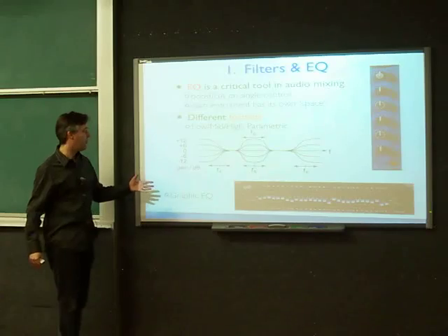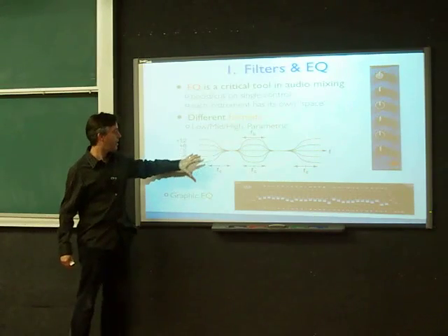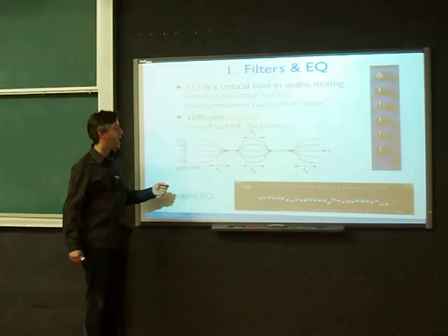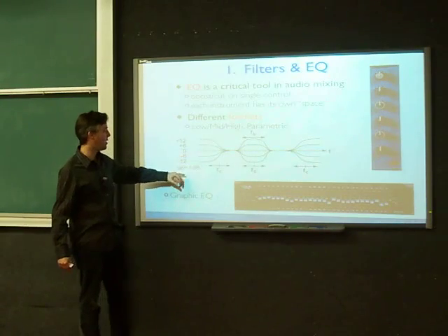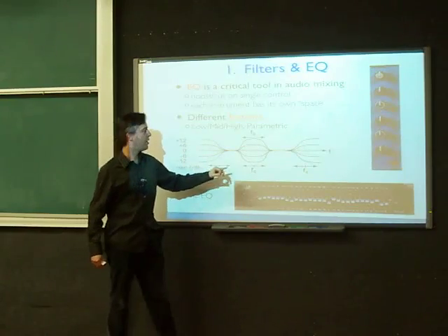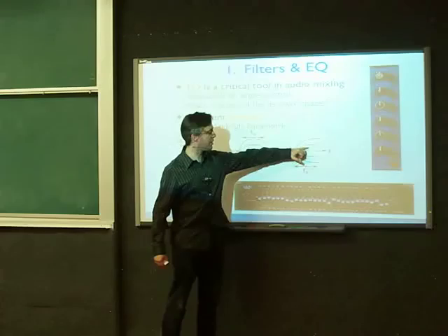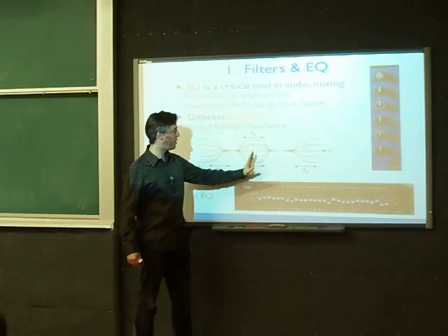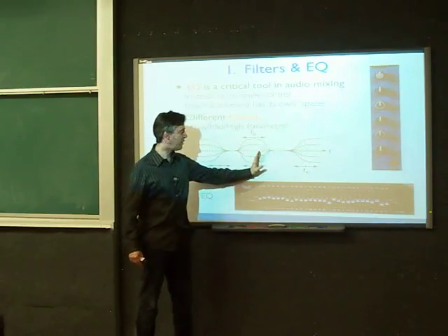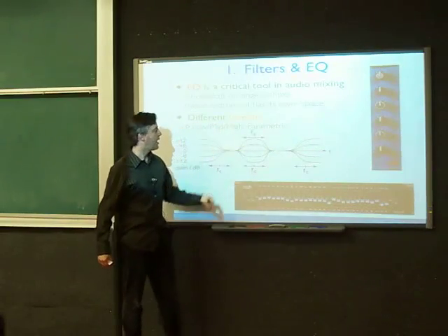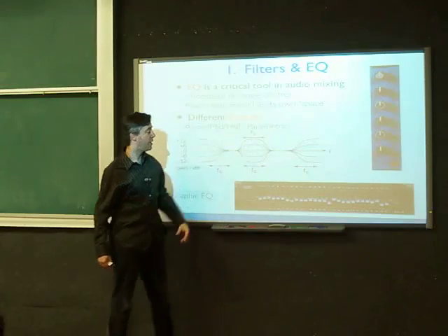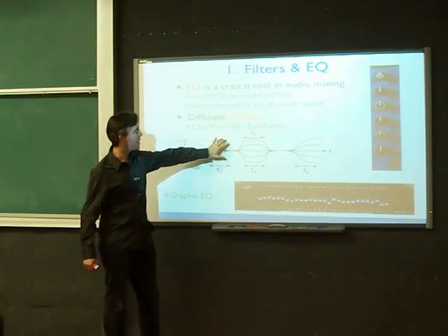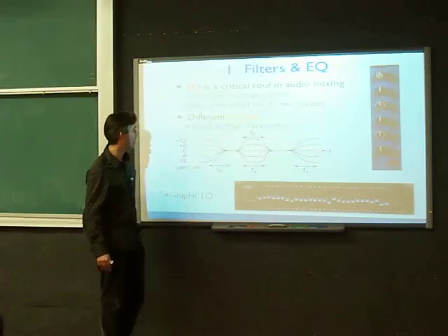Typically you'll have a parametric filter, a filter where you can control it by these parameters, but its frequency response is going to look something like this. If this is frequency and this is gain, then you've got filters which you can either boost the frequency or cut the frequency. Then you'll have several filters at different frequencies, but you can also change the center frequency or the cutoff frequency for these ones, and maybe even change the bandwidth. So on a mixing desk you'll typically have some fixed filters, but then one or two sections of parametric filter that you can vary like this.